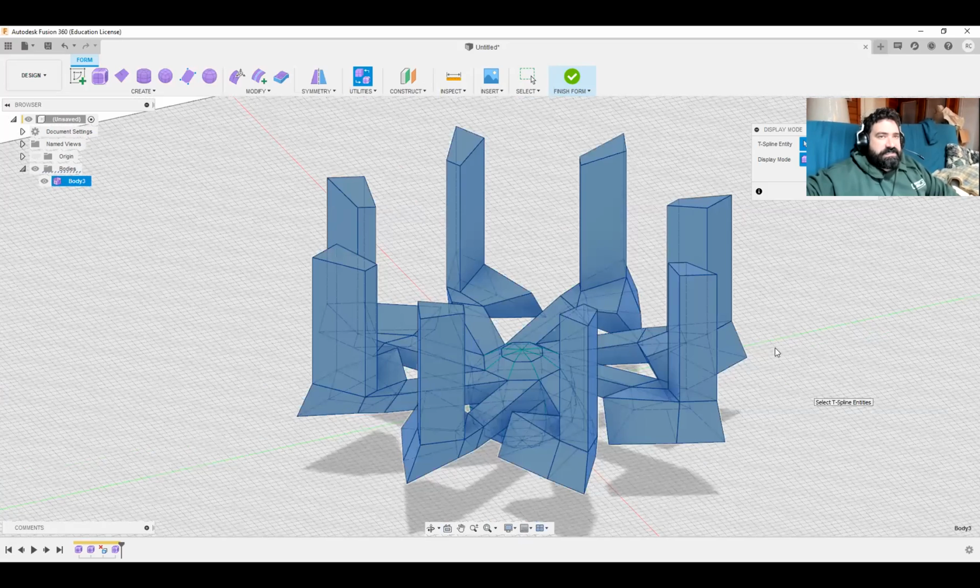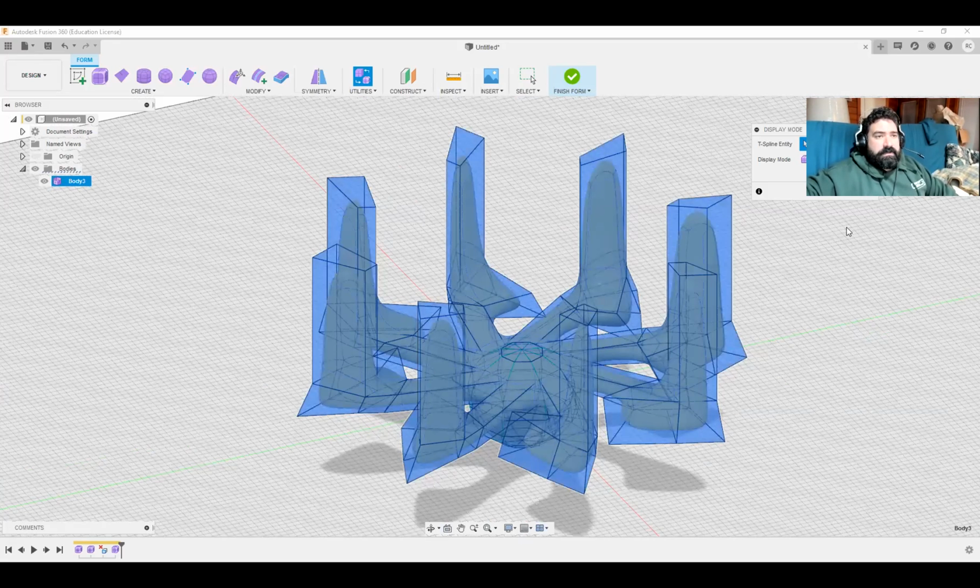What that's doing is it hasn't actually made an alteration to your project. What it's doing is it's simply changing the views so that if you wanted to get more complex, this simplifies your form to where you can more easily work with it, and then you just change the view back to smooth, and it will recalculate everything. So this just helps save some computing power. You could do both with the control frame selected, so it's a little bit easier to grab sections.